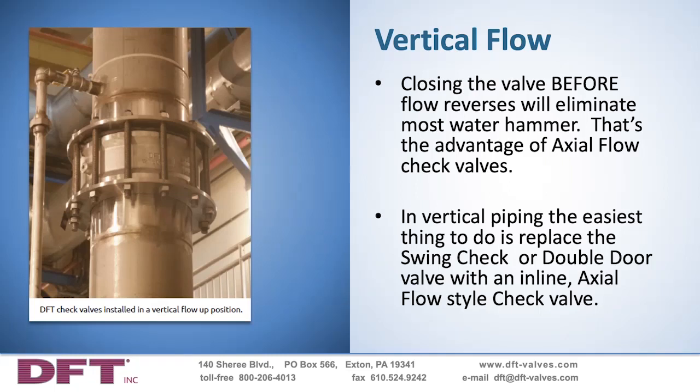Axial flow valves utilize either helical or conical spring designs, and they are very easy to make custom and to dial in small increments of closing force differences within the various spring types. And so this is the advantage of the axial flow design, the ability to customize a valve for a specific application.